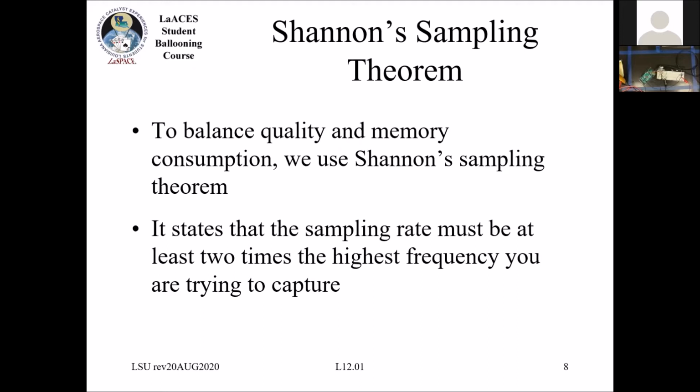So once you get a number of, okay, I want to see a 1 degree change and I expect it to change by 5 degrees over a minute. Okay, now I can assume then I only need to sample 5 times a minute. And then you double that basically to make sure that you're sensitive to any changes.